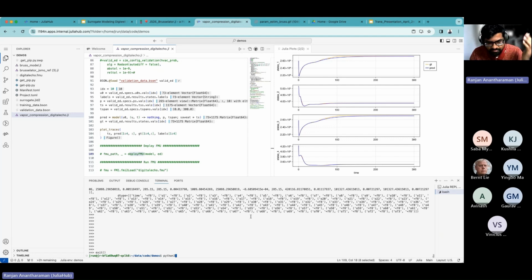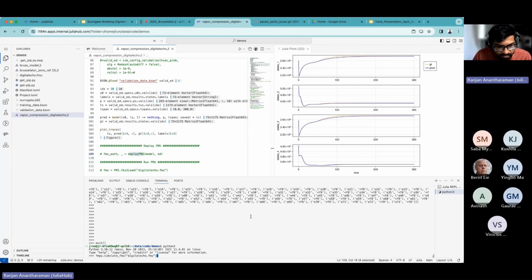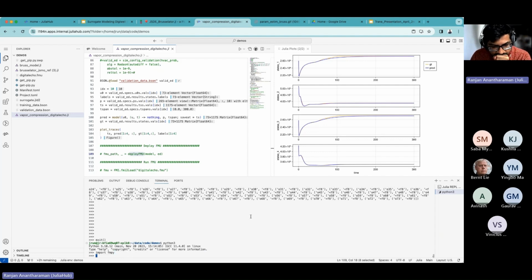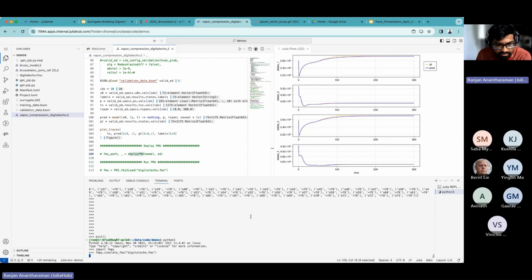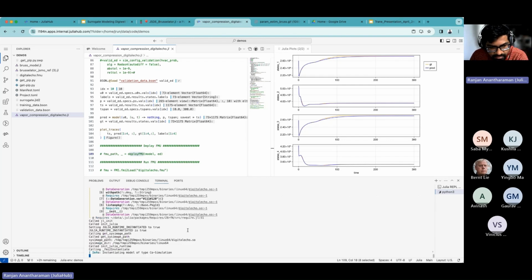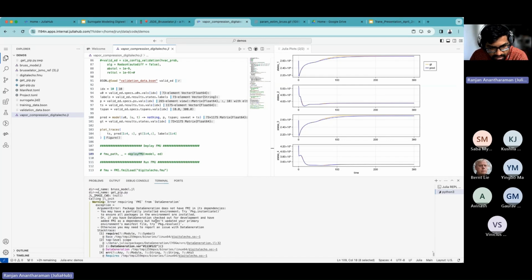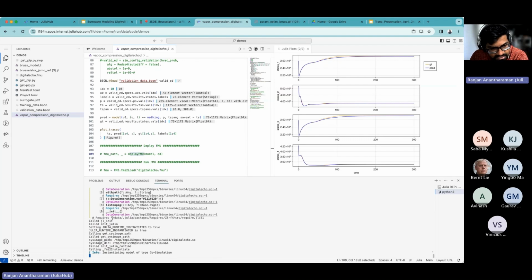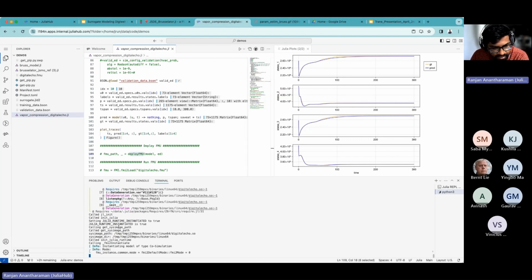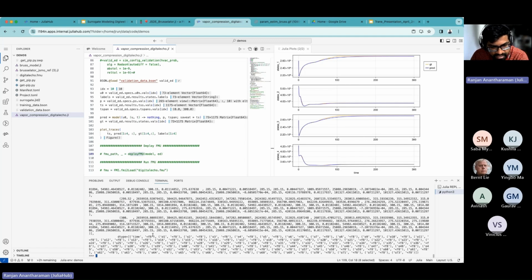So I'm importing this from Python, and running the FMU with a well-known FMU simulation tool called FMPy, and you can just hit simulate FMU, and then this will load up. You can see there's a warning here that we need to clean up, but you can import this FMU here, and after some logging information, it'll run fairly quickly and give you the results.